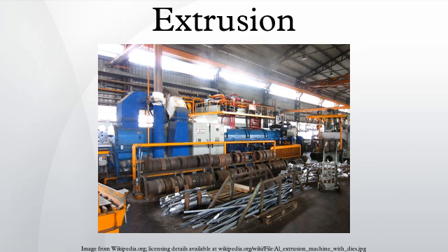Hydrostatic extrusion. In the hydrostatic extrusion process, the billet is completely surrounded by a pressurized liquid, except where the billet contacts the die. This process can be done hot, warm, or cold, however the temperature is limited by the stability of the fluid used. The process must be carried out in a sealed cylinder to contain the hydrostatic medium.